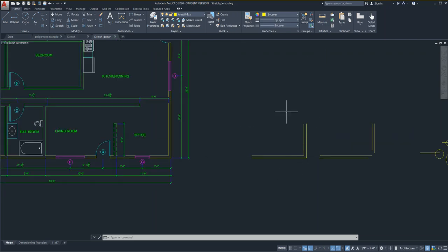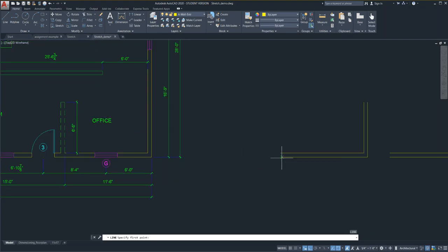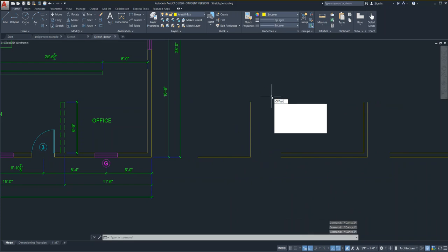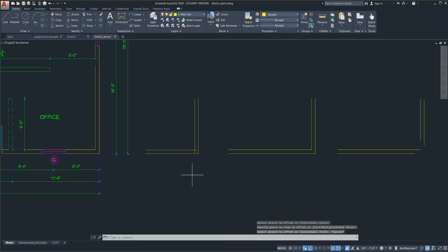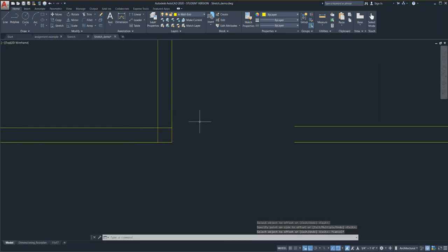This exact condition is seen over here on this little floor plan, okay? Now, what I'm trying to illustrate here, let me just draw a quick little line over here, okay? What I'm trying to illustrate is something we have talked about, and let's see, there we go. You've used the offset command before, obviously. Offset 5 and 1/2 inches, enter. And if you were to offset these individual lines, right, to create this floor plan, you would get something that looks somewhat like this, right?